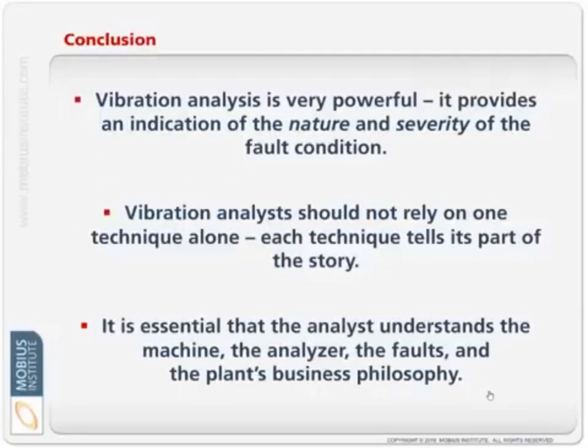So, in conclusion, vibration analysis is very powerful. It provides an indication of the nature and severity of the fault condition, and it has been used in every industry all over the world for many years. But I would like to reinforce that vibration analysts should not rely on just one technique alone. The spectrum is useful, but there are other tools.